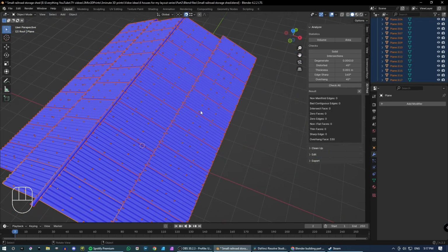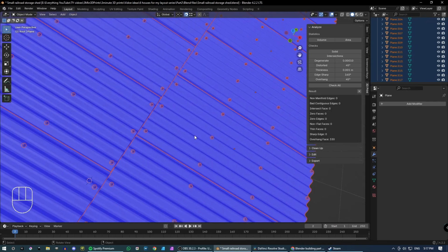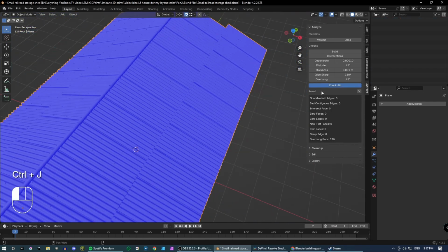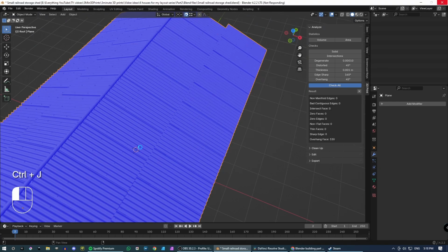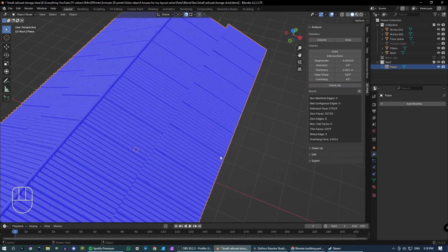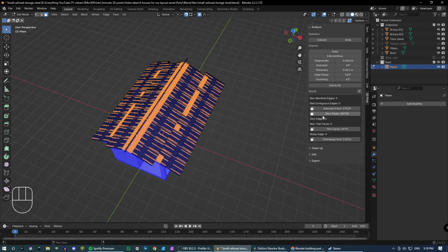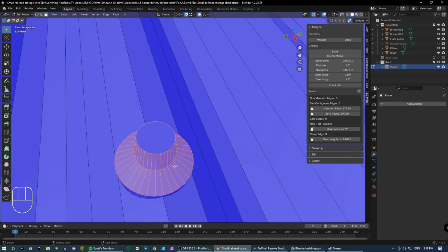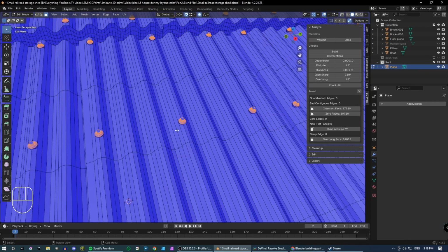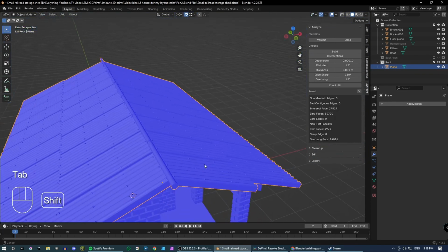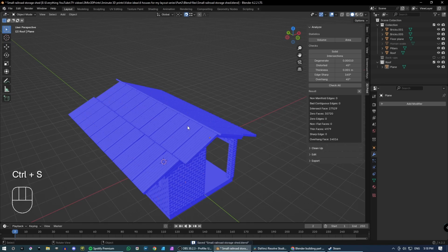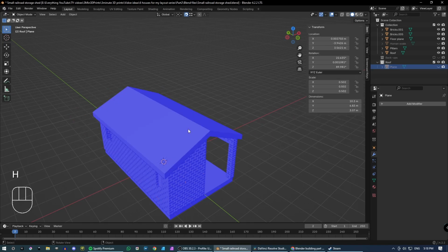So I select everything and join them together again. It will have many bad intersecting faces now, but after booleaning everything together, it should be good. Let's just check it anyway. No non-manifold edges, which is good, but yeah, a ton of intersecting faces. This is probably way too dense. I should have decreased the resolution. Anyway, I think I'm happy with this, so let's hide it for now.